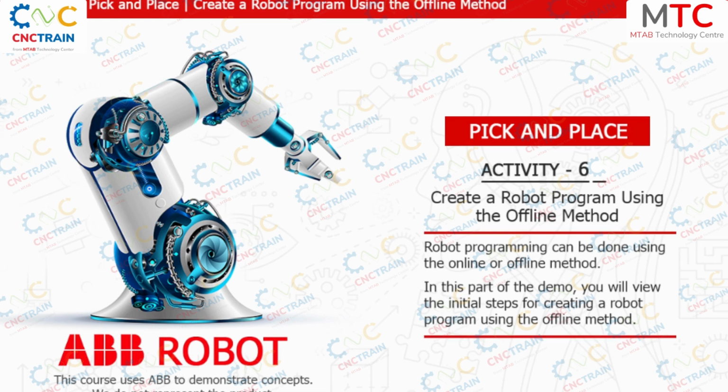Robot programming defines the workflow of a robot and it can be done through the online or offline method. Programming done without being connected to a robot or a real controller is called offline programming. The robot movements are programmed as pose-to-pose movements, that is, move from the current position to a new position. The path between these two positions is then automatically calculated by the robot. Programming done by connecting to a real controller is called online programming. Online programming also implies that the robot is used to create positions and motion.